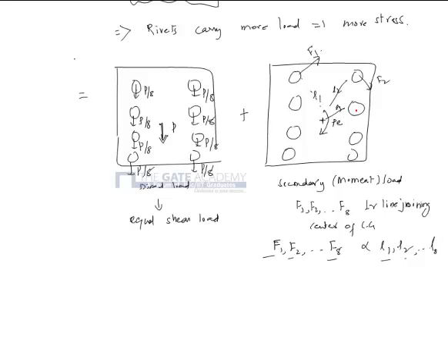Okay, so this is how the direction will be. You can see that once you join all these lines from the center of each rivet to the CG of the rivets, you'll find that L1, L2 and these extreme lines joining A, B, H and G are longer.